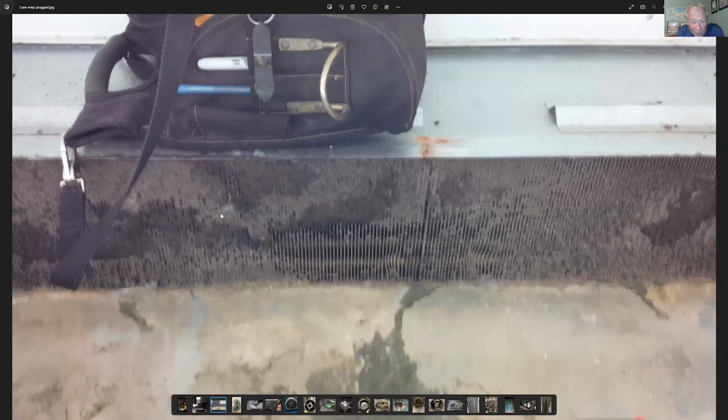I'm not sure what they're doing or not doing in this store, if we are talking about a supermarket application. That's a big one, that honeycomb. Remember, a lot of times you're using natural convection to move air around the evaporator, but the honeycomb becomes plugged and dirty, and it's just an airflow thing.